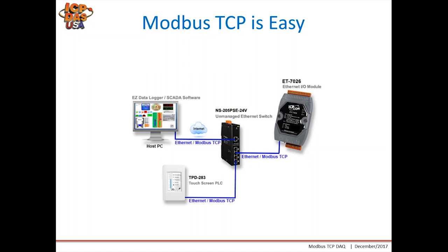The SCADA software or master controller must have a driver or built-in communication to allow for Modbus TCP communication as a master, and the slave devices have defined Modbus address tables based on the manufacturer and of the hardware, and the connection from the Modbus master defines the connection to the slave device by its IP address, usually port 502, and the Modbus address of that specific node. And then you reference the register or registers which you'd like to pull data, both read and write.